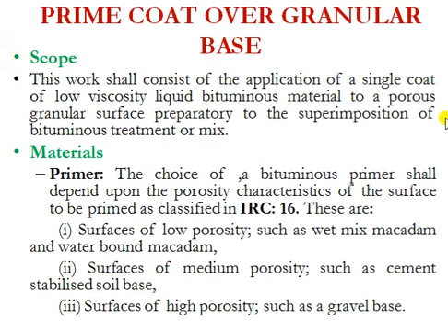So now let us see what is a primer coat. Primer coat over granular base. This work shall consist of application of a single coat of low viscosity liquid bituminous material to a porous granular surface preparatory to the superimposition of bituminous treatment or mix.